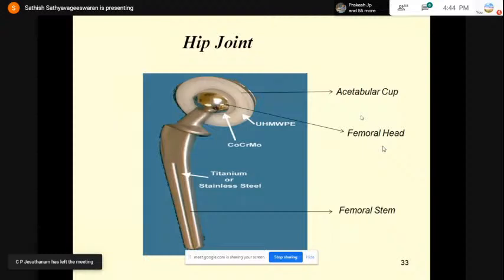So people thought of searching for some other group of alloys, and among all these materials, this titanium 13 niobium 13 zirconium alloy is said to have a modulus somewhat close to that of the bone. It has a modulus of around 77 GPa, which is slightly more than that of the bone. Even though some other materials have a modulus very close to that of the bone, the reason for not choosing them is the presence of tantalum. If tantalum is more, it is expensive. That is why people didn't use some other alloy, even though its modulus is very low.